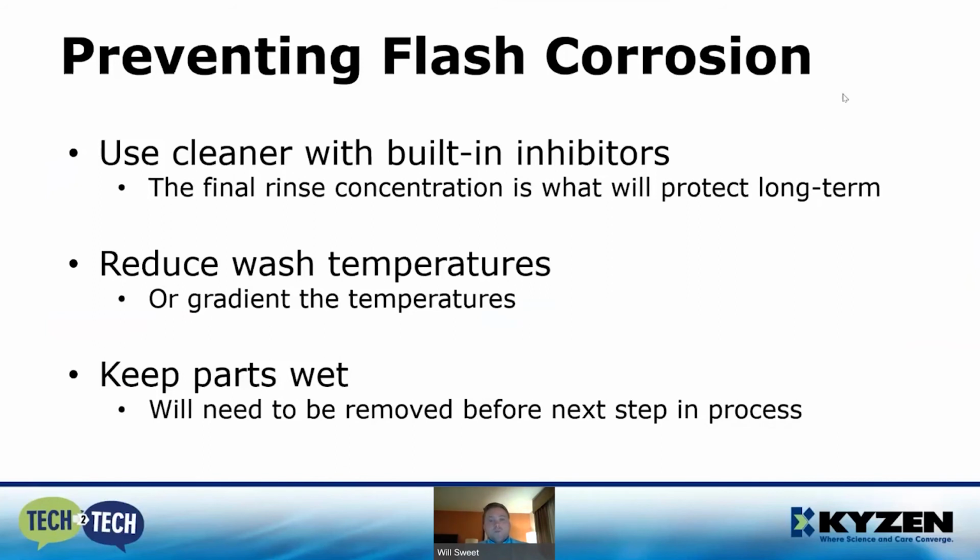And also, while your parts are wet, they're not going to corrode. So in most applications, you're going to have to remove the wetness, the water, the cleaning, and the cleaning chemistry that you put on the part. At some point, you're going to have to remove it. But it's worth knowing that while it's wet, it's not going to corrode.